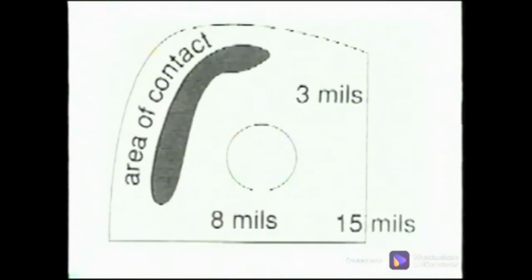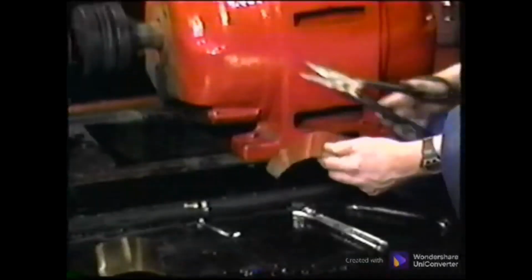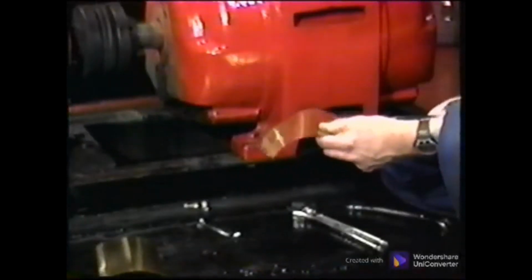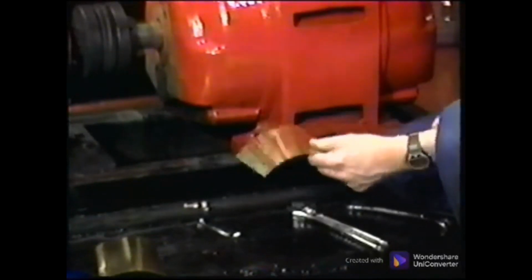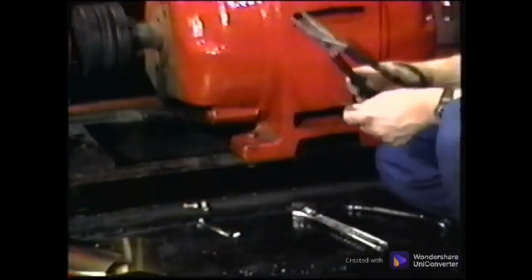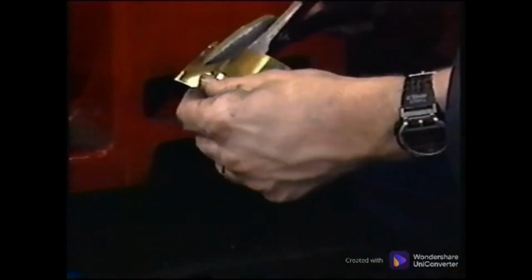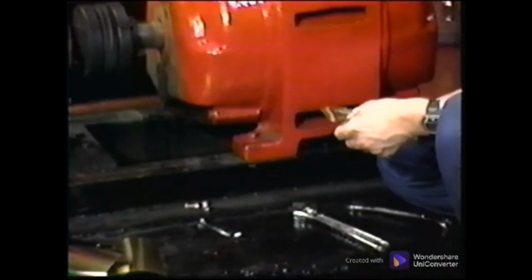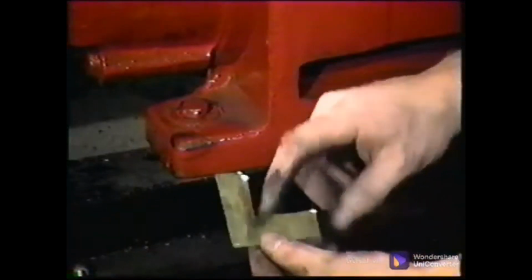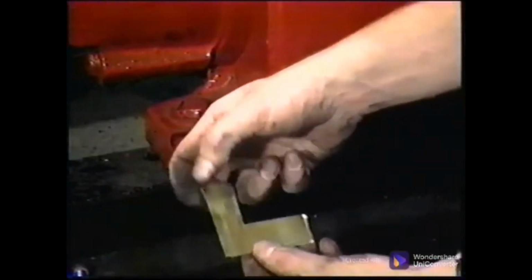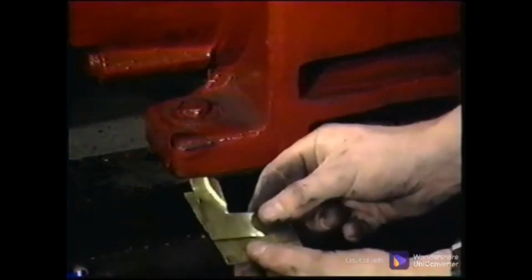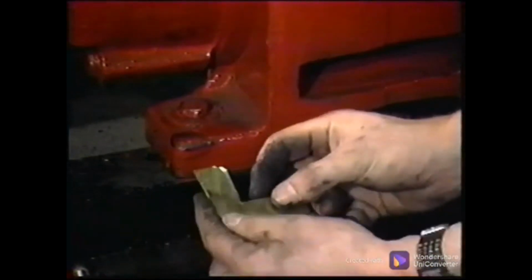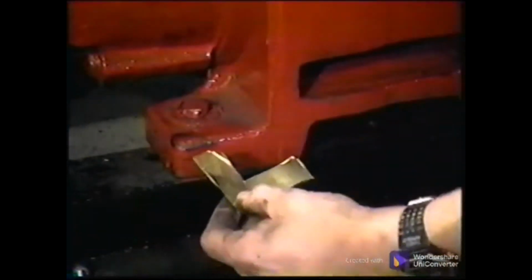Record this measurement for this corner of the foot and continue measuring each corner of the foot to determine the profile of the clearance. After the measurements have been recorded for each of the 4 corners of the foot, cut shim stock to fit the profile. Where one side is thicker, use 2 or more layers of various thicknesses of shim stock. Depending on the measured clearances, the shims may need to be square, C-shaped, L-shaped, a straight strip, or any combination to create a customized wedge. Remember to sandwich the thinner shims between the thicker ones.